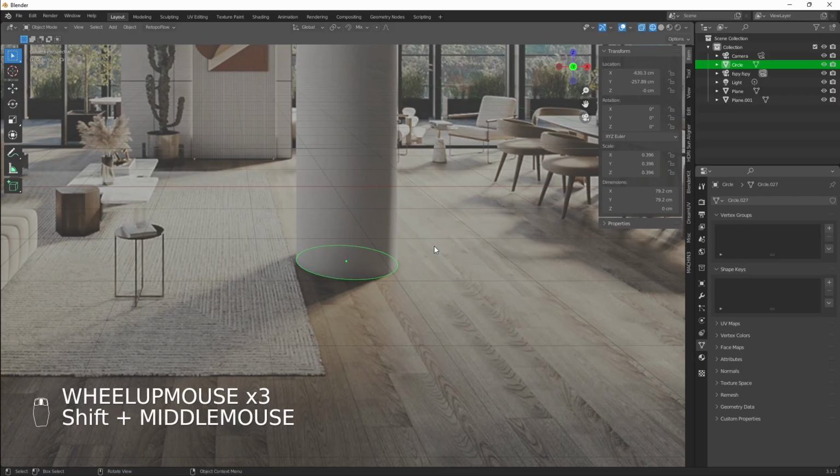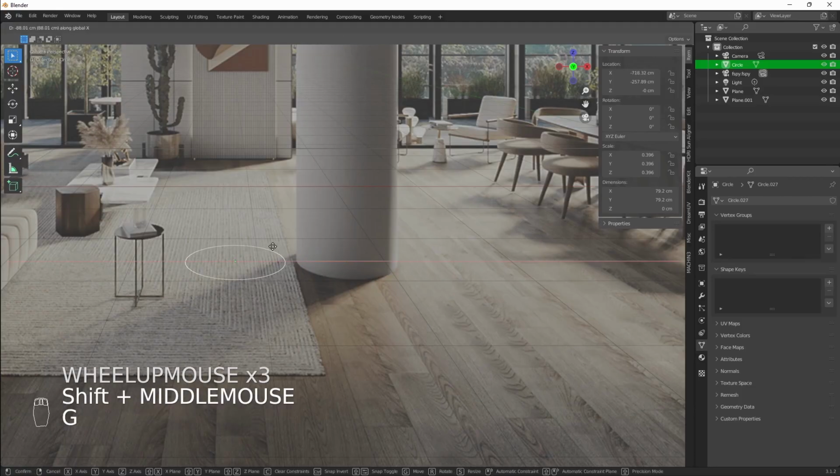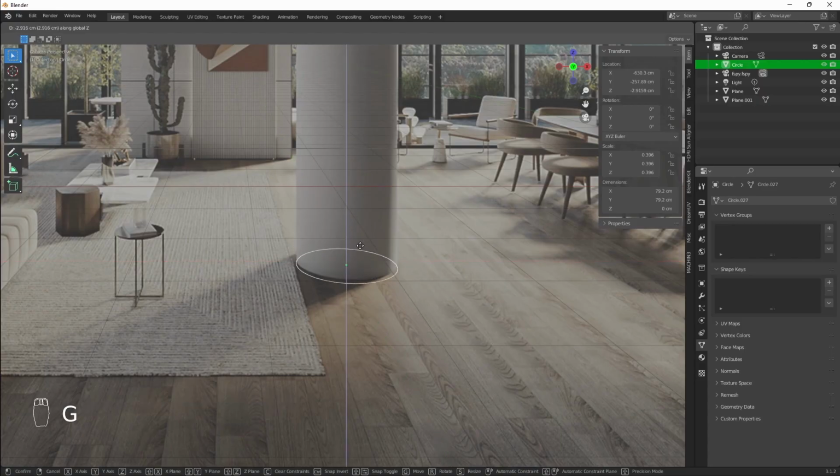And that's why I'm hammering the point home that in this part of the process, almost every grab operation should be constrained. So you press G followed by X, Y, or Z, or to select the whole plane, G followed by Shift X, Shift Y, or Shift Z. It's very easy to forget about it, especially when you make slight adjustments, so let it better become your habit.